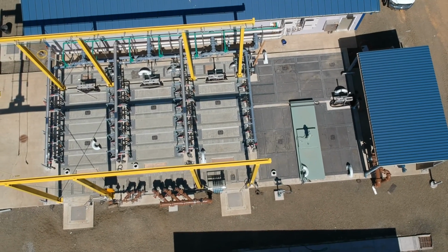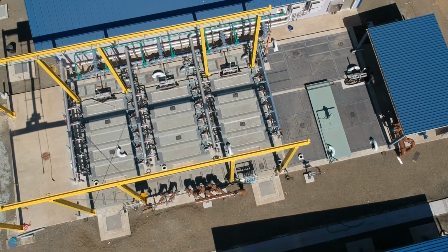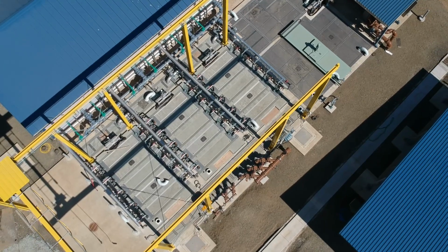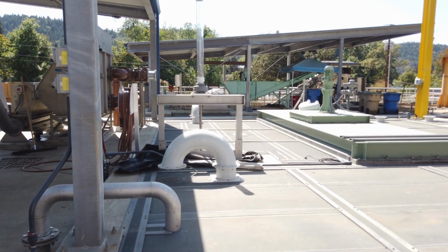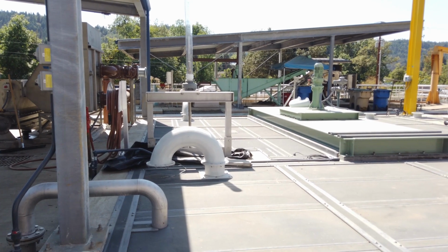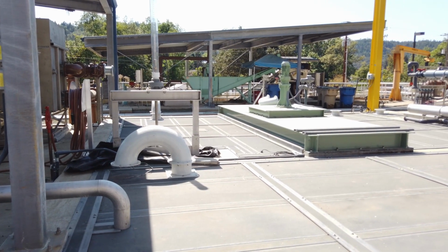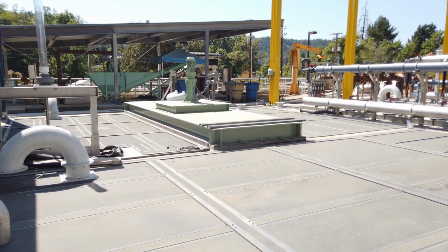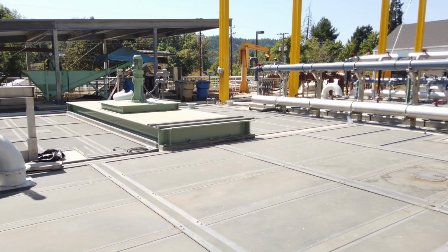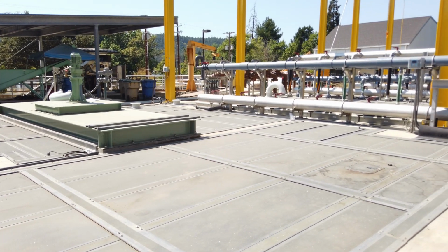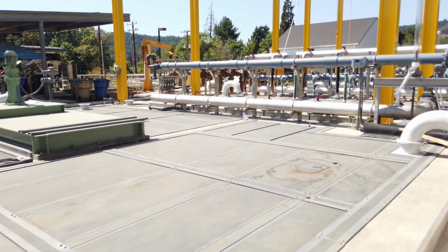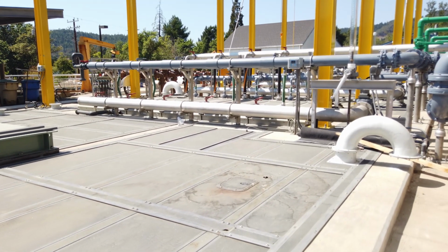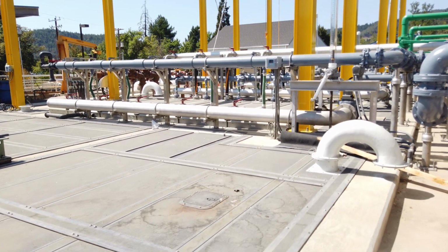We have an ammonia limit of less than 5.4 milligrams per liter during the summertime when discharging to the South Umpqua River. To ensure proper airflow, we have a submerged, continuous dissolved oxygen probe. It's located in the mixed liquor and measures the instantaneous DO concentration. We're targeting a DO of about 2 milligrams per liter. The pre-aeration blowers, which we will later see, have variable frequency drives that adjust the blower speed based upon the actual DO in the pre-aeration tank.